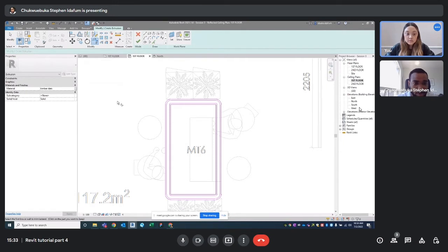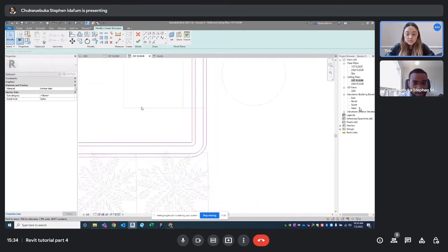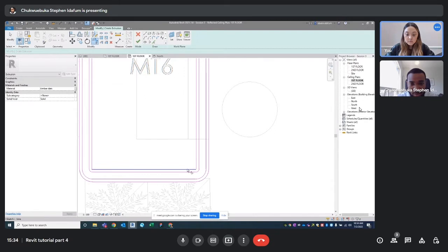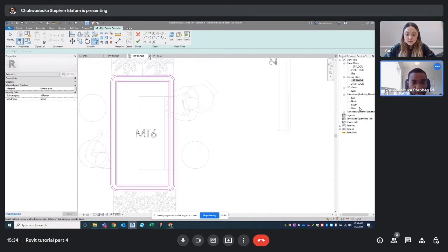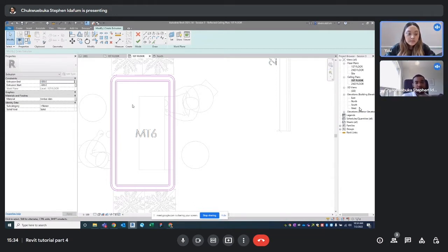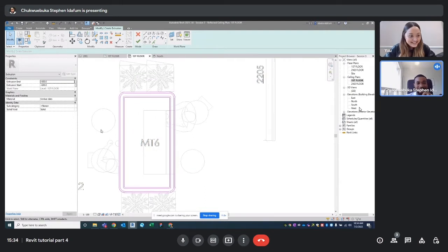Okay, let's control Z. Extrusion. Okay, sorry, my bad. So it starts at what? Minus 600? Minus 600 to minus 800. Okay. So when we work on the ceiling plans, we go minus because we're working down from the ceiling. Yeah, okay. You're smart. Okay, let's give it materials.